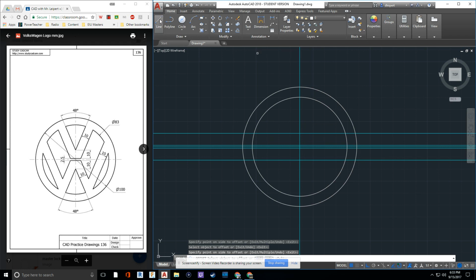Now that we have that, I'm going to use my layer for my line here, snap at that intersection. We can go straight up with that one. Select that one line, type in RO for rotate. Let's specify this is our pivot point, and we can rotate with F8 off.